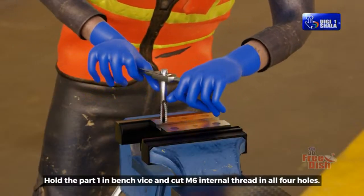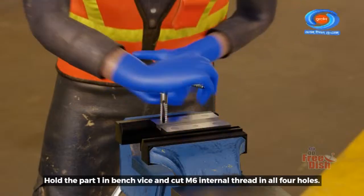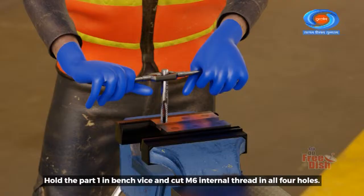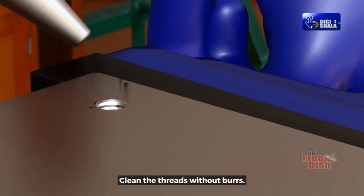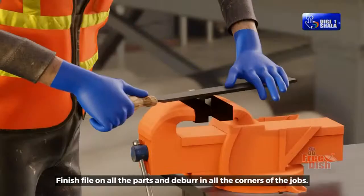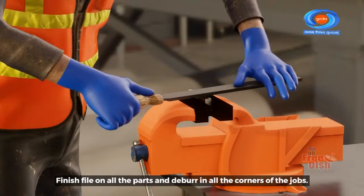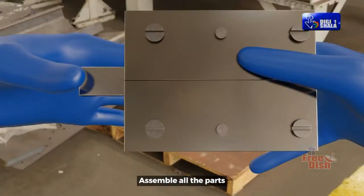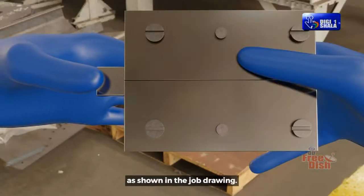Hold the part 1 in bench vise and cut M6 internal thread in all 4 holes. Clean the threads without burrs. Finish file on all the parts and deburr in all the corners of the jobs. Assemble all the parts as shown in the job drawing.